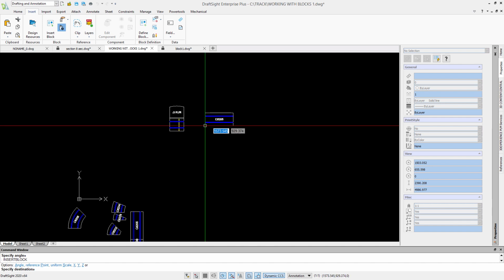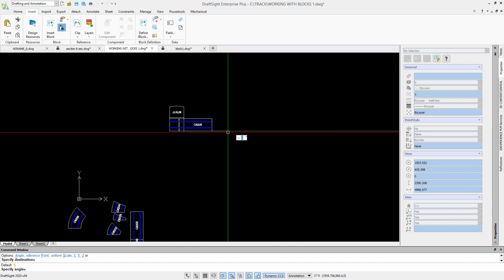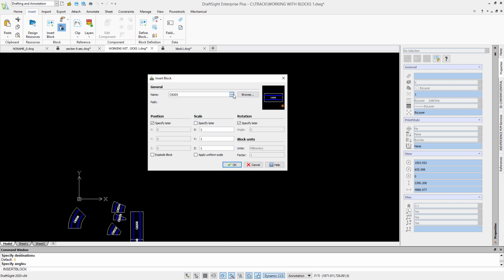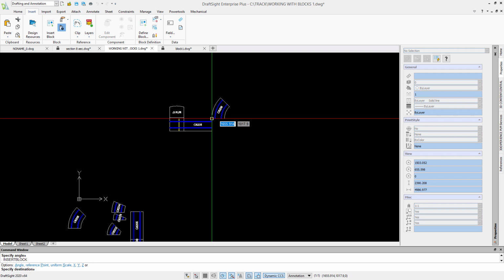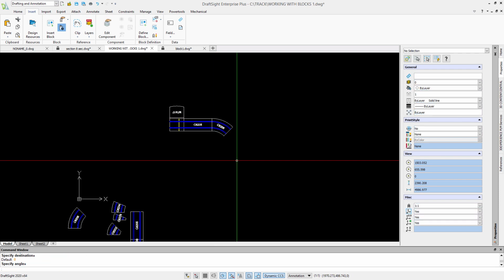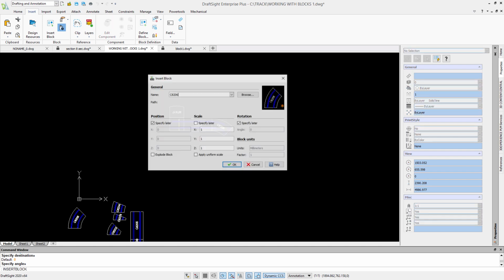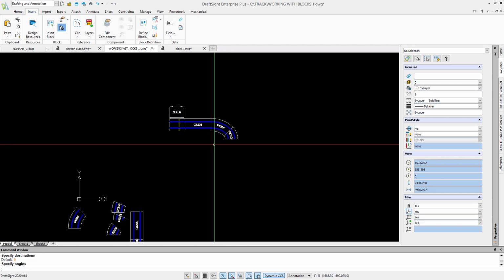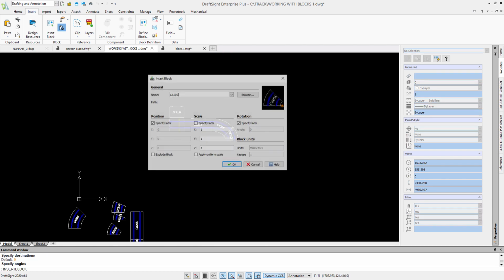Now I've got the first part in, I can continue to add additional blocks. So we've added a straight section there. Let's have a bend. We'll gradually build this up by adding in this large radius, gradual bend. And let's make it a sharper bend, so it tightens up as we get into the apex of it.